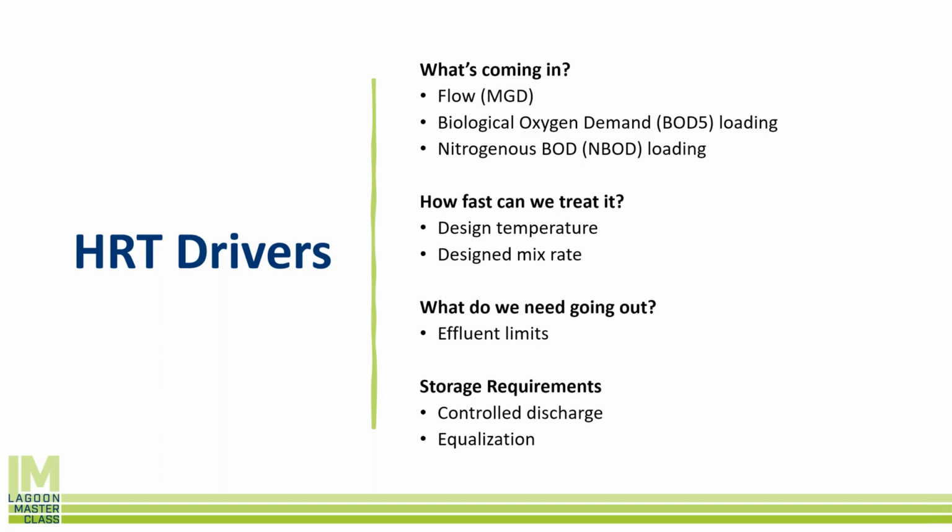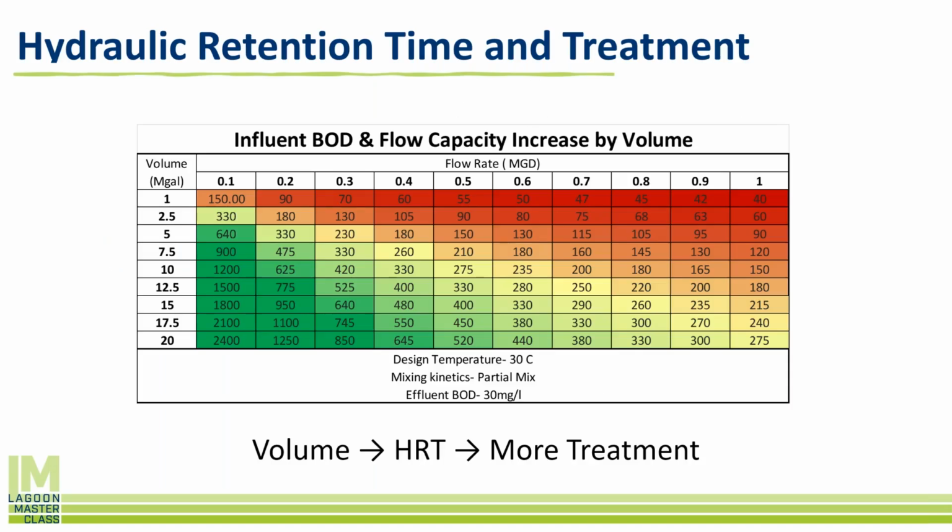And then there's also storage requirements. In some cases, lagoon systems will have a controlled discharge lagoon where they want to store water until a certain point, or equalization. We want hydraulic retention time simply for storage or EQ. And it's a really interesting interplay too.